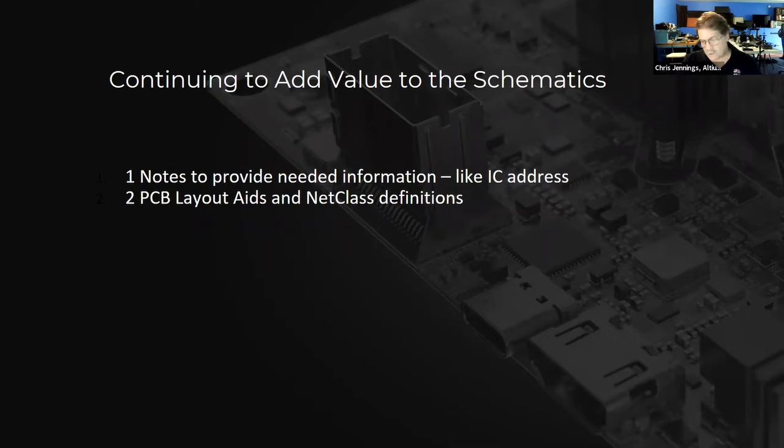Your power budget is much lower when you have lower voltage. So there's a couple of things you can't change. You can't change basically the capacitance that you're driving, because that's based on the geometry in the chip. But the more you lower the voltage, the lower power you have, and that makes it easier because it's less heat. But that was driving the IC industry, and the IC industry therefore drove the design industry.